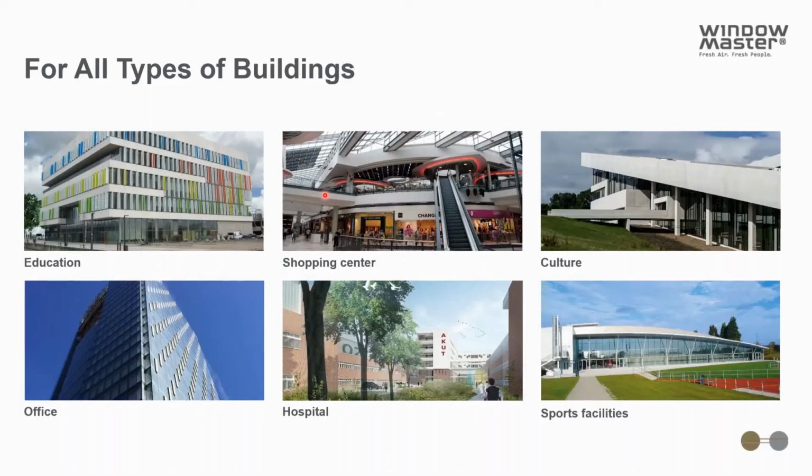This really goes for all types of buildings. Natural ventilation has some limitations, but it can be used to some degrees in most projects. If you take a hospital, for example, it doesn't only consist of operation rooms and so on, but it also has lobbies, atriums, waiting areas, and so on, which are spaces ideal for natural ventilation.